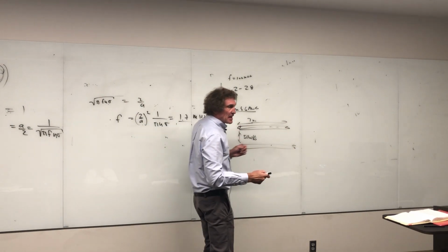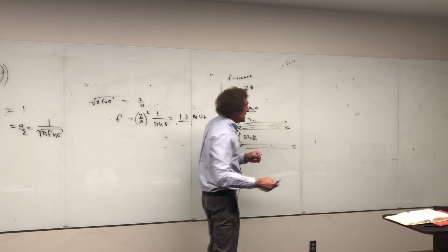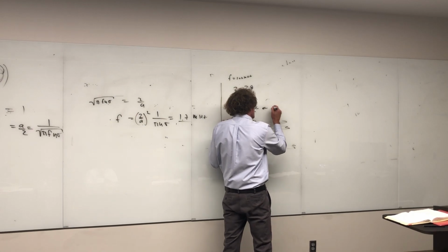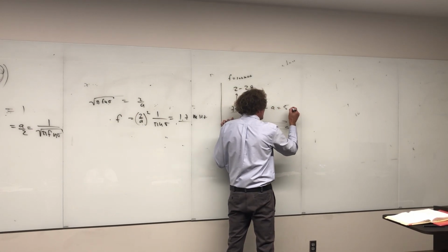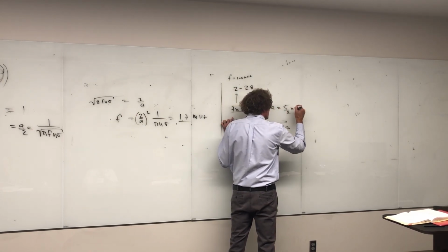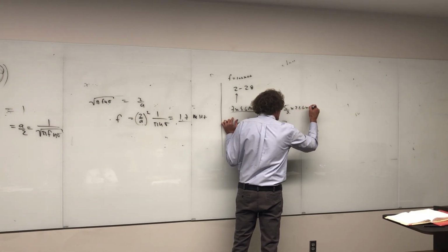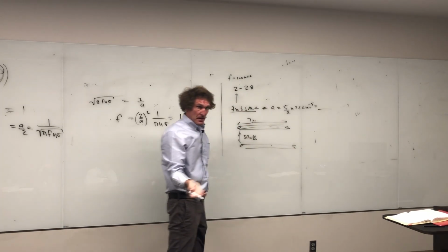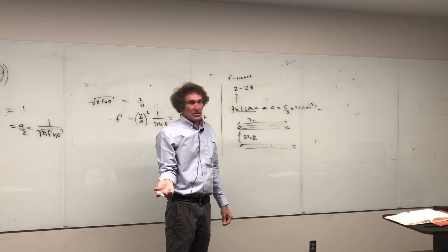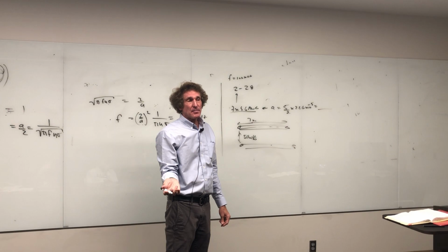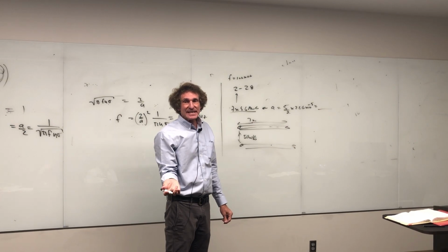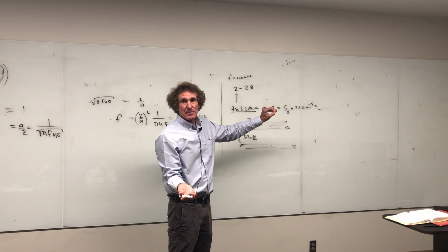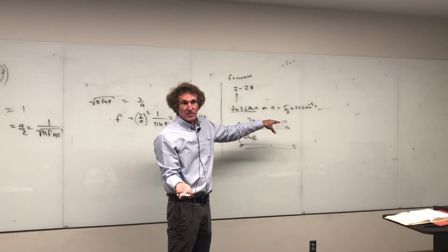Now, at 36 AWG, that has a certain radius in mils. It's 5 mils divided by 2 times 2.56 times 10 to the minus fifth. That will be the radius in meters, right? I don't know what that is, but you all follow my train of thought here? Now, the next thing we have to do is find out what the skin depth is to see if the skin depth is of the order of that or if it's much, much bigger.